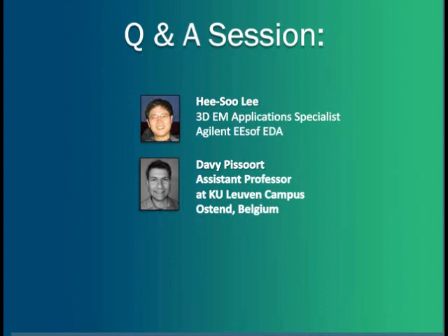Well, the general way that's been put forward in the last years by several experts on EMI, which I also follow, is to try to avoid having different grounds. You have to be very careful with different grounds. You definitely have to avoid going over them with traces, and you have to try to have only one high-frequency ground if possible.